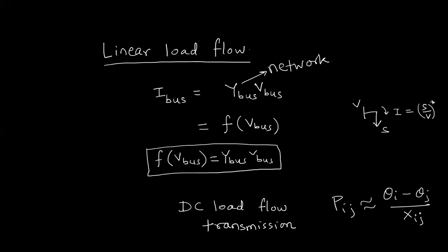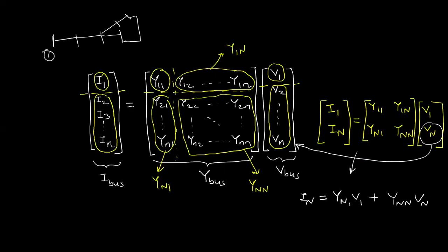In this expression, I bus equals Y bus V bus. I bus basically represents current injected into the bus, but we are writing the expression for load currents. That load current should appear in the I bus matrix with a negative sign, because I bus represents injected current, but the load is instead taking current away from the bus. That is why the load equation should be equal to negative of I bus. So the correction should happen here.